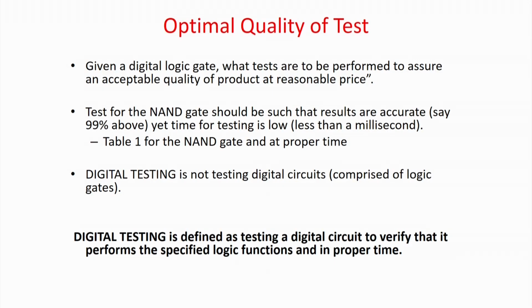So what are the basic paradigms, or what do I basically require for test? Many people say that we require 99% plus fault coverage or guarantee. We will tell you what fault coverage is. I give more than a 99% guarantee that whatever chips I send you as proper chips are correct. That means out of 100 chips you manufacture, 30 may have defects, that is a yield problem. But when I say 99% accuracy, it means if I am sending some 70 chips, there should be 99% probability that whatever I am sending as a proper chip does not have any manufacturing defect. That is the idea.